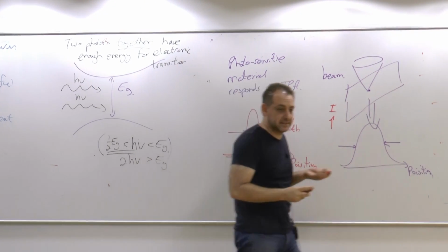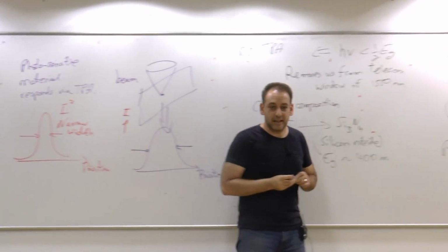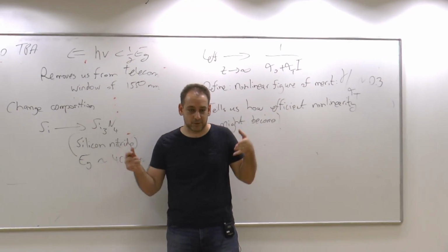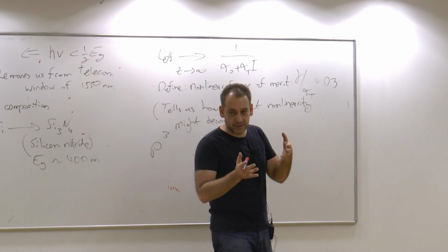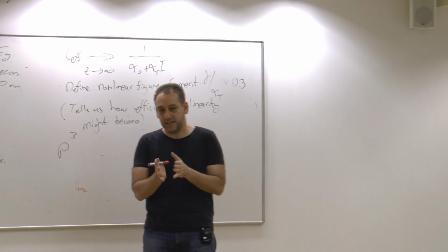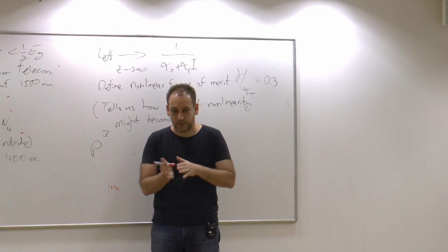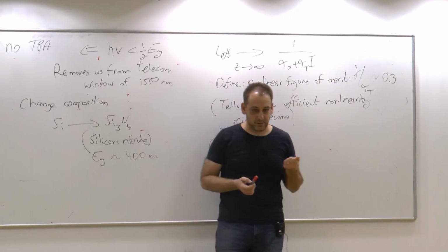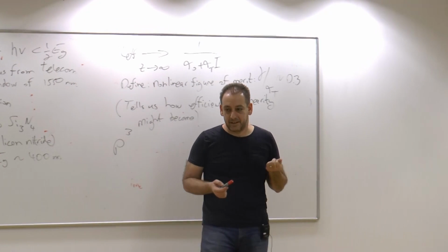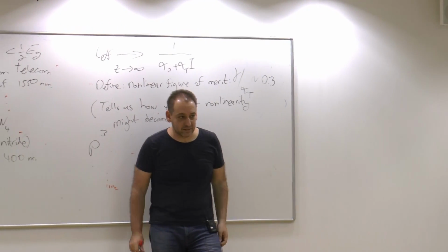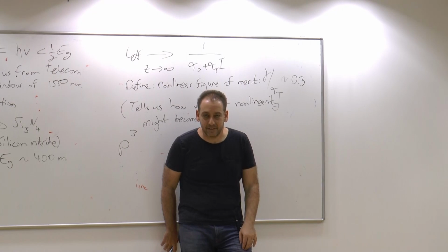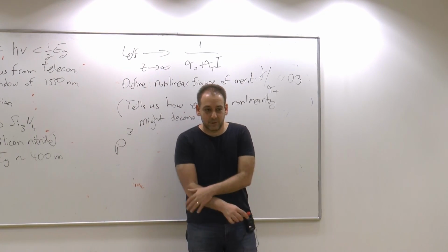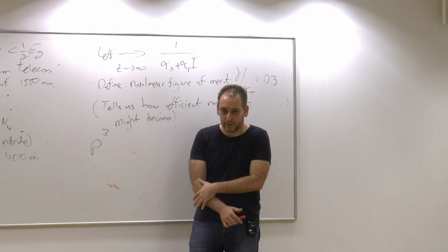So in various fabrication protocols, actually two-photon absorption is quite useful, because you can take the same light source, which has the same diffraction limit, and use it to define smaller patterns, because we're using a resist material that responds via TPA and not due to single photons. In fact, maybe even not all the students from my lab know that, but the waveguide protocol that we have for writing in chalcogenide glasses is a TPA protocol.